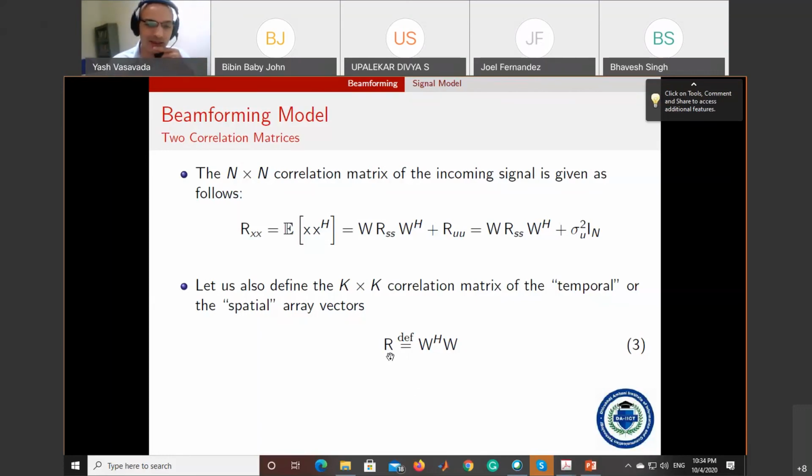So in case of this uniform linear array, or in case of these DFT filters, the elements of R are completely determined by that sinc function. And you know that if I am sampling the sinc function very closely together, then yes, the diagonal element I will get is 1. But the off-diagonal element may be as large as 0.99 if the second frequency is super close to the main frequency. And so we cannot always hope that this R will look like a diagonal matrix.